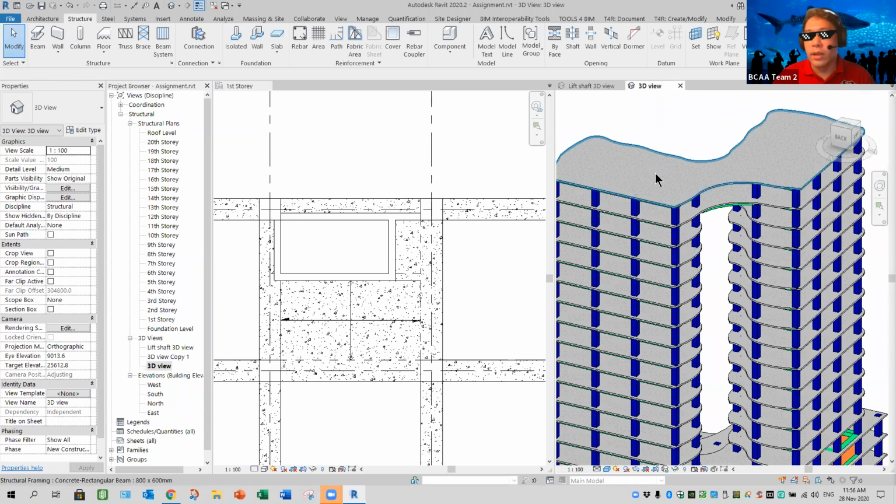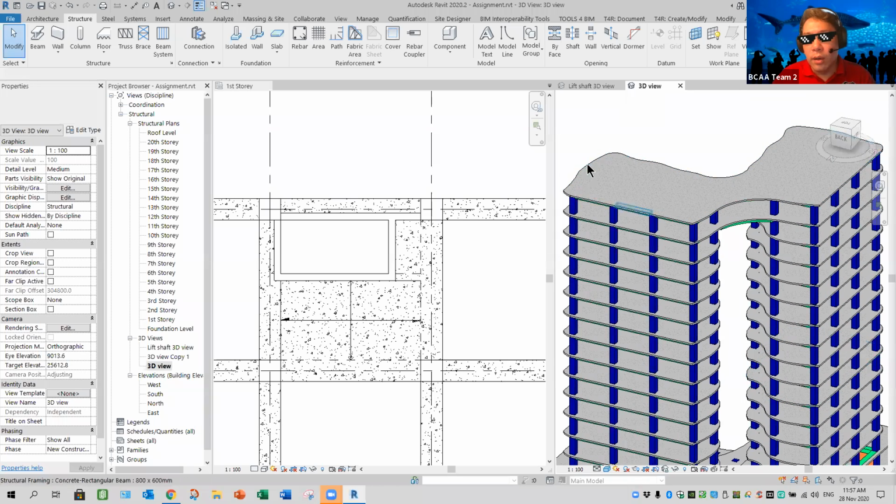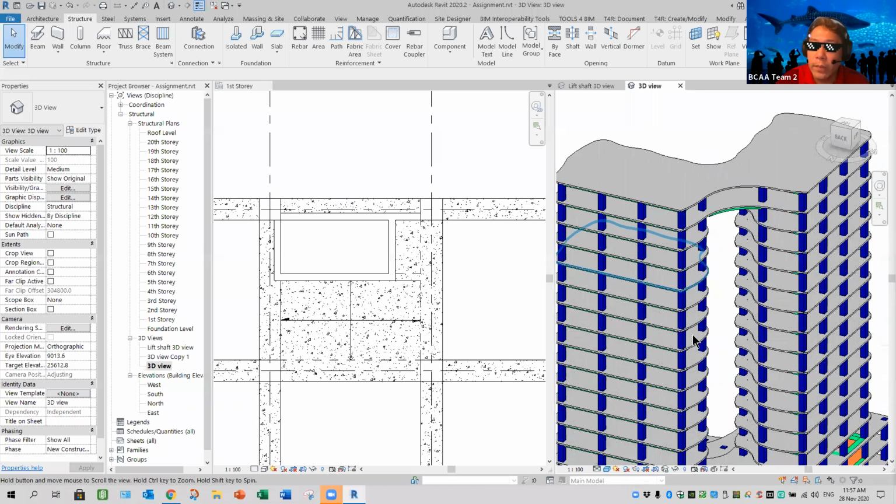Then the motor room should be outside on the top level. Then here, whether you like to add what we call a parapet wall or not, I think that's individual. Normally there should be one, because here there is normally some piping, ducting, whatever. You don't want things to fall off your rooftop. But because a parapet wall is an architectural component, when you draw an architectural wall, it will not show. So you guys got to be careful.